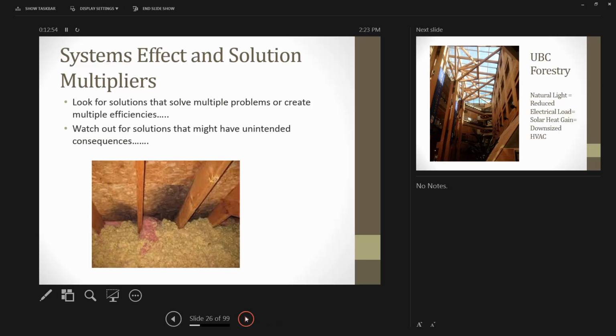And it happens a lot in existing buildings and existing building weatherization. In the desire to create greater energy efficiency, what will happen a lot of times, without a good understanding of building science, is you'll see people tighten up the building envelope and create significant unintended consequences, not understanding where the vapor drive goes, and sometimes even creating potentially harmful situations.